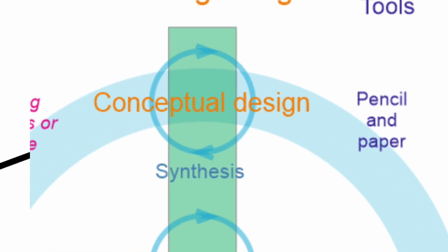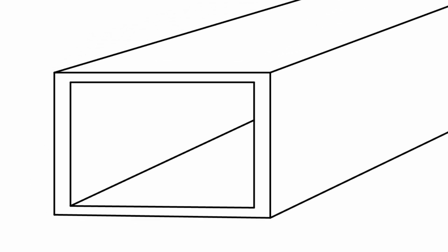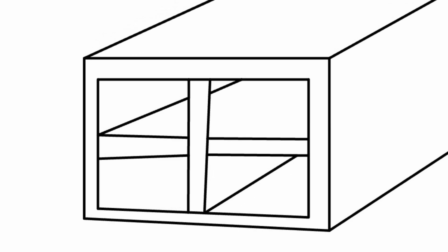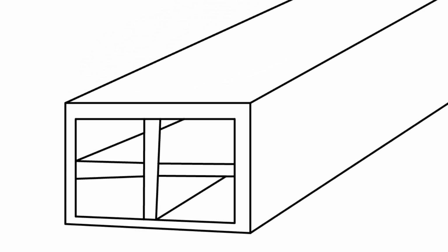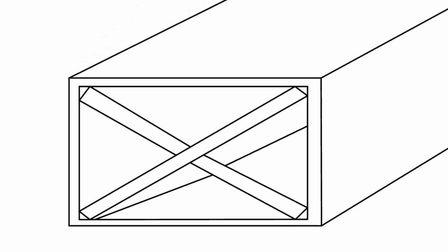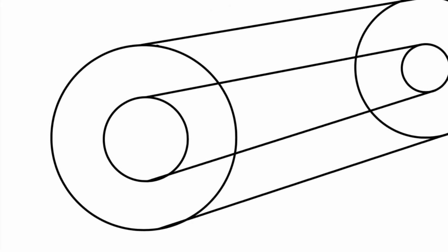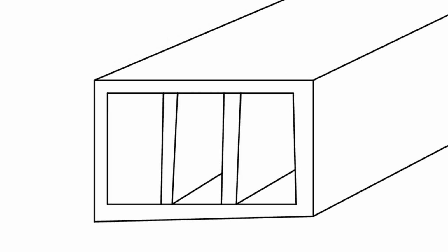When looking at conceptual design, we needed to initially understand structural performance requirements, for example, bending, which involves tension and compression, as well as torsional resistance. We looked into multiple spar structures, such as triangular spar and rectangular spar. We realized that the rectangular spar had more resistance from external stresses and was easier to build and test.